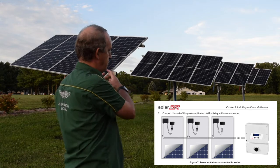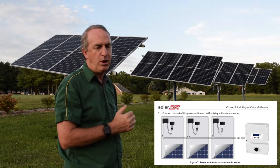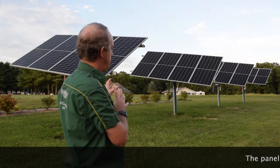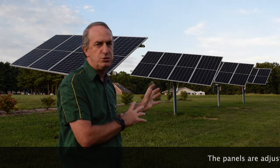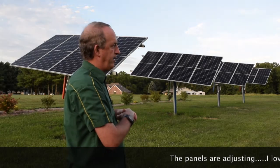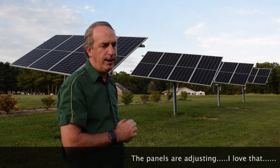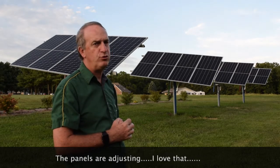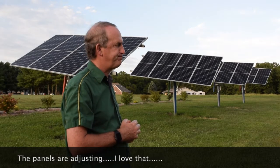Then, depending on the length of the wiring that goes to the barn, you get losses for that. Basically, these systems are designed so that you should be using 10 gauge wire, and no matter how long you run, you can survive, and the losses won't be too great with the 10 gauge wire.